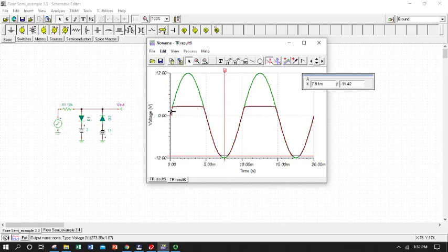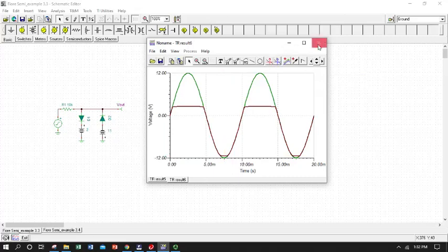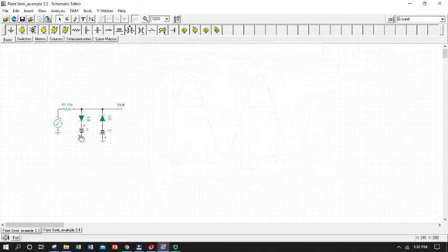So what we're doing is clipping the amplitude of our resultant waveform. We're limiting that amplitude by giving the current an easy path to follow and not allowing ourselves to develop a bigger voltage drop over that initial resistor, effectively. So that is clippers in a nutshell, with bias offset.